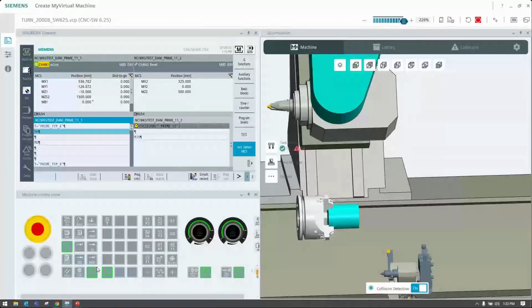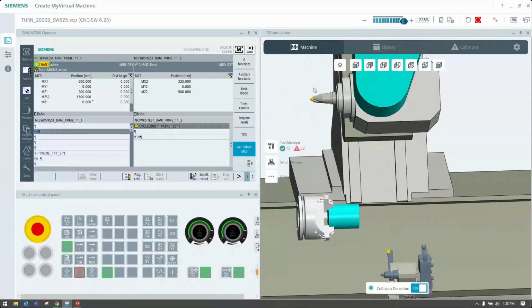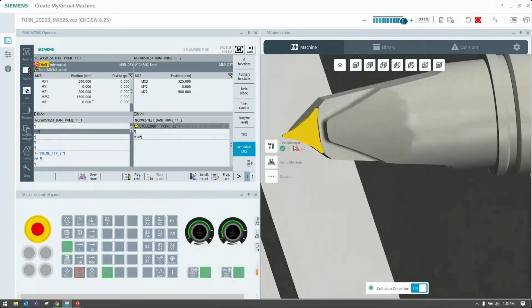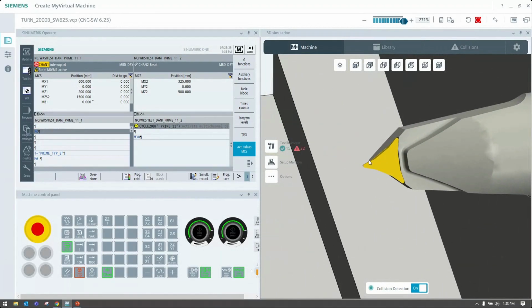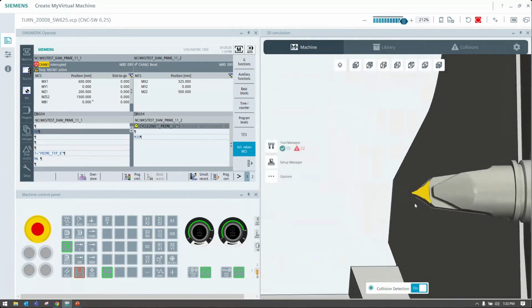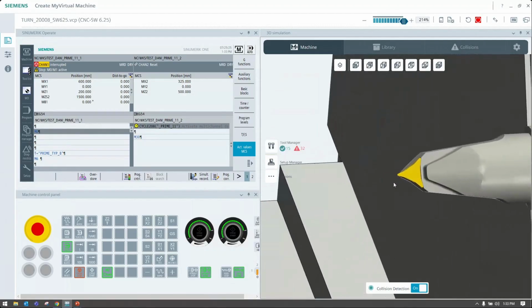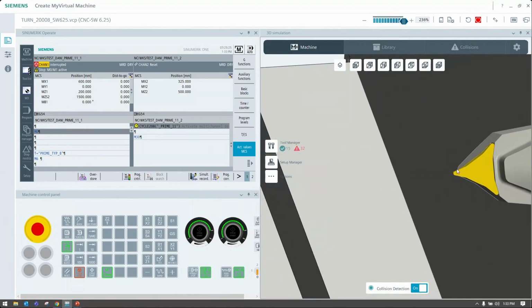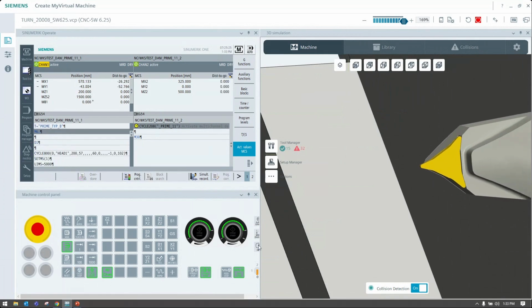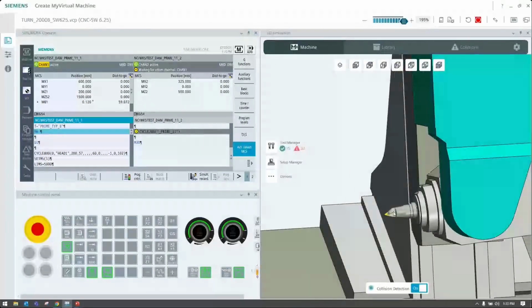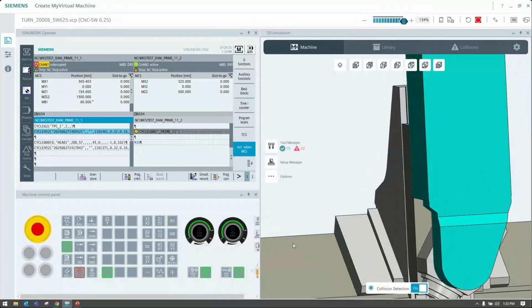So the first one I'm going to pull out, this is what the two different types are. This is the A type. So we have the star style. We can either use this side of the insert or that side of the insert. So definitely a lot of capability there. So what am I getting, three cutting edges out of that tool? Yeah, effectively, one, two, oh yeah, three cutting edges. I get it. You're back turning with it. You can actually turn in both directions with that tool, right? Yep. And then this is the B style. Oh, sorry.